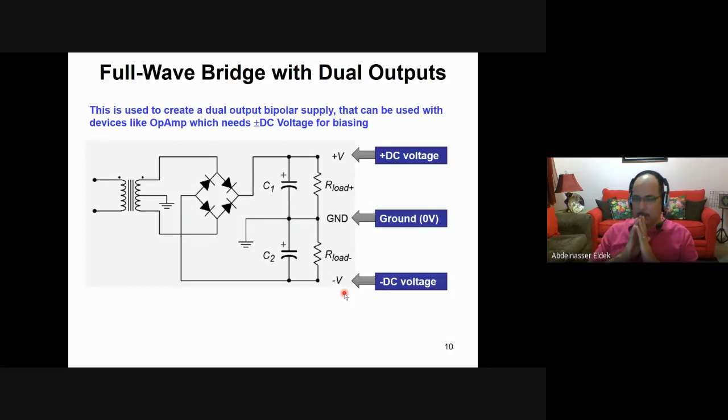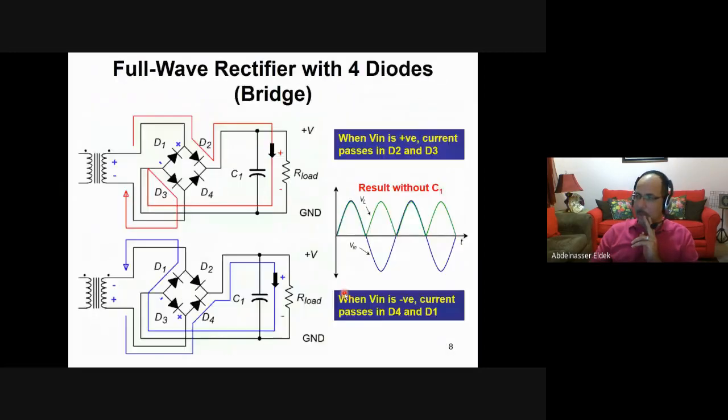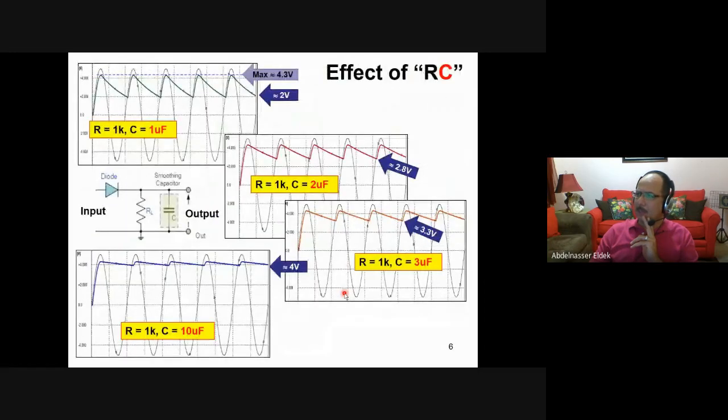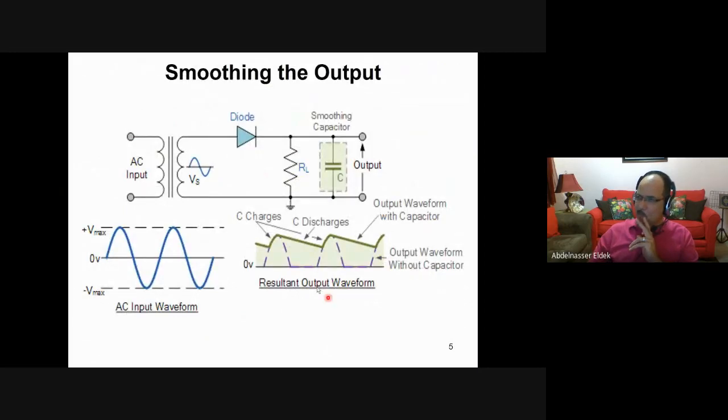Before I go to the next one, let's return back to this circuit. Actually, what happened here is that this circuit is acting as a peak detector also. So this is not only a half-wave rectifier, but also a peak detector, which means that it detects the peak, the maximum, because it's almost curve fitting here. You connect this peak to this peak, this peak to this peak.